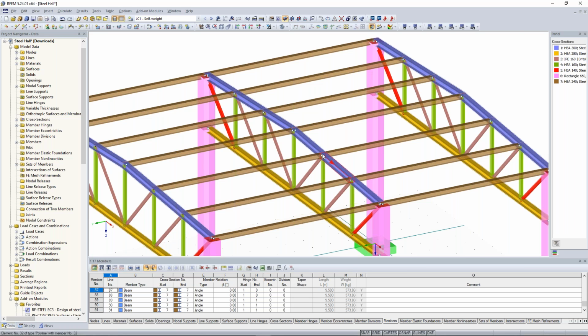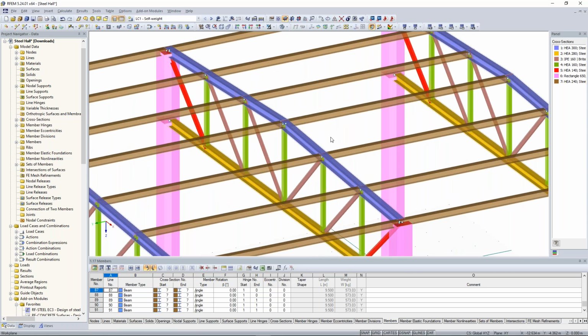Yeah, I can consider scissor hinges, and each of the two member pairs transfer moments in its continuous member direction, but they do not transfer any moments to the other pair. So only shear forces I want to transfer to that beam.